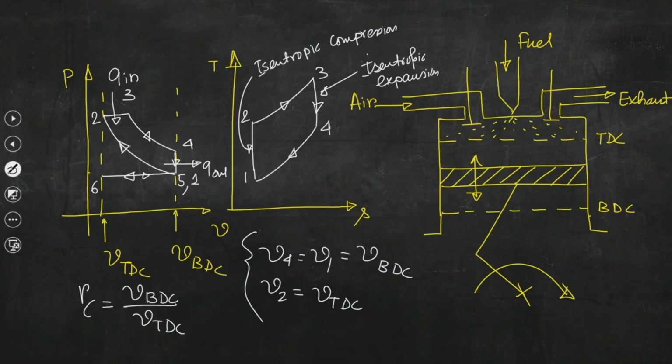So, in the process of combustion, volume of the working substance is getting changed from V2 to V3. So, the ratio of this change in volumes is known as cut-off ratio pertaining to the combustion of CI engines. So, if we write in the next slide that cut-off ratio